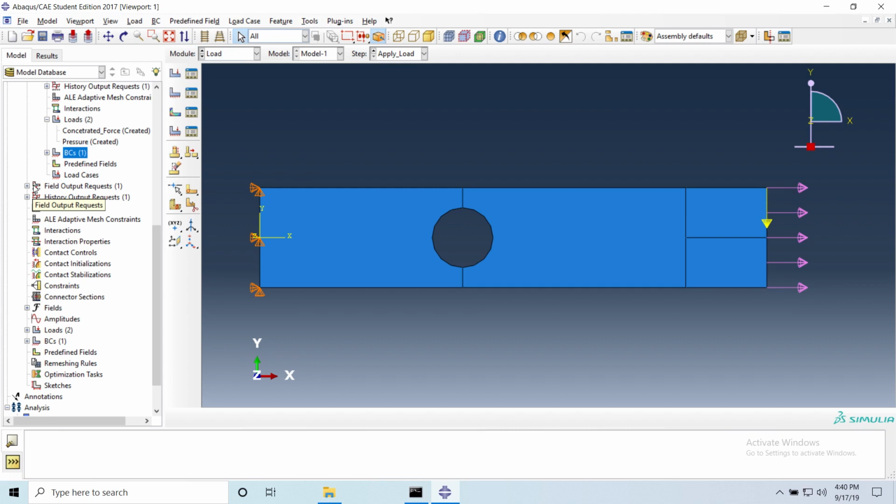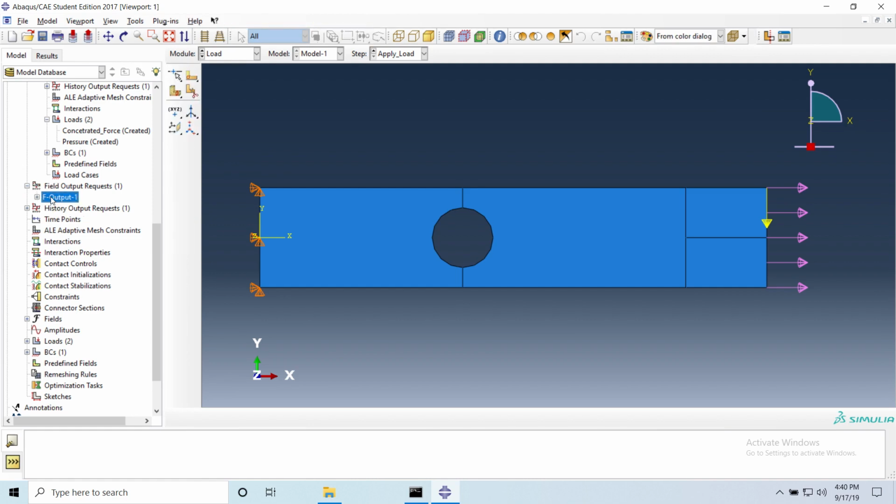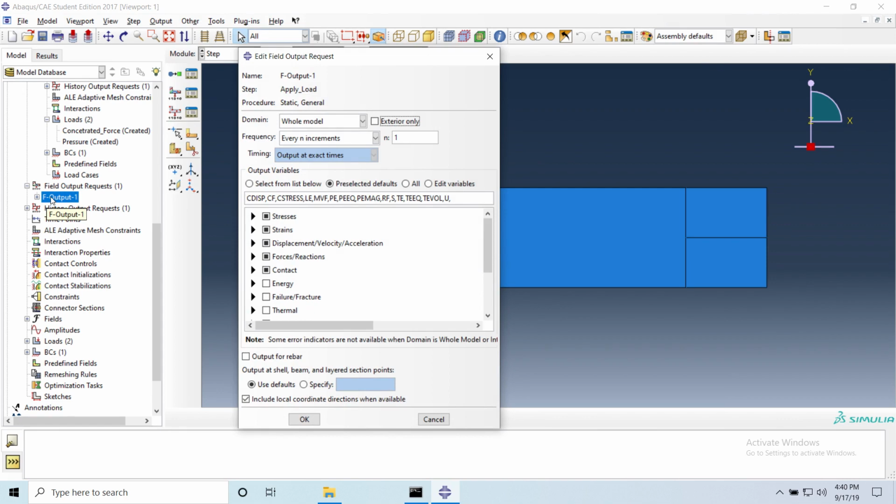So for now, I'm only gonna ask about stresses, strains, displacements, but later, whenever we go into cracks, we are gonna have to request the energy release rate and other types of energy for our analysis, and then we understand what's going on with the structures. So for now, Abaqus has by default created a default field output. If you double click in there, those are the output quantities that you are gonna compute after you compute the displacements. Everything is computed from the displacements.